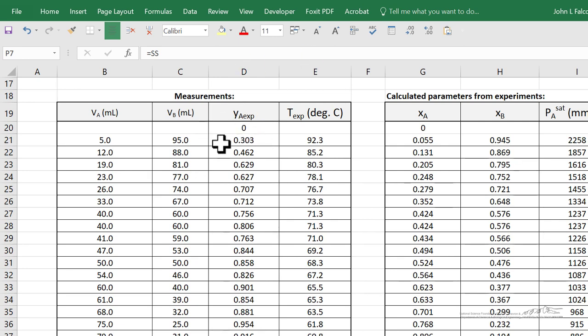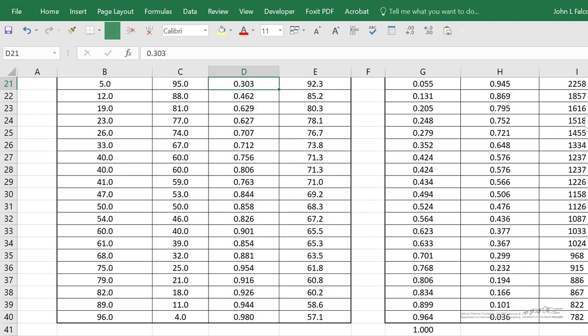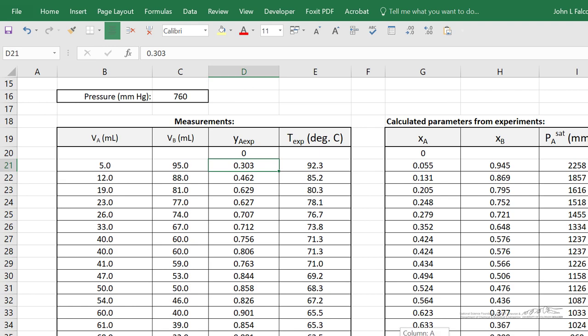And we're assuming that the very small amount of the vapor, which is present in a total reflux as a condensate, is small compared to the liquid, so the liquid composition we calculate from our starting materials is pretty close to the liquid composition at equilibrium. We then measure these mole fractions of vapor phase and the temperature, and then we calculate from these measurements.